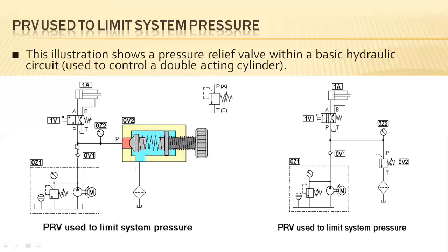and the system specifies that only 2 bar of pressure is sufficient for operating this actuator for the forward and return strokes. So hence at that particular time we have to reduce 1 bar of pressure. Hence this pressure relief valve plays a major role, as it will set the pressure within this gauge to 2 bar, and the next 3 bar of pressure will be entering here,